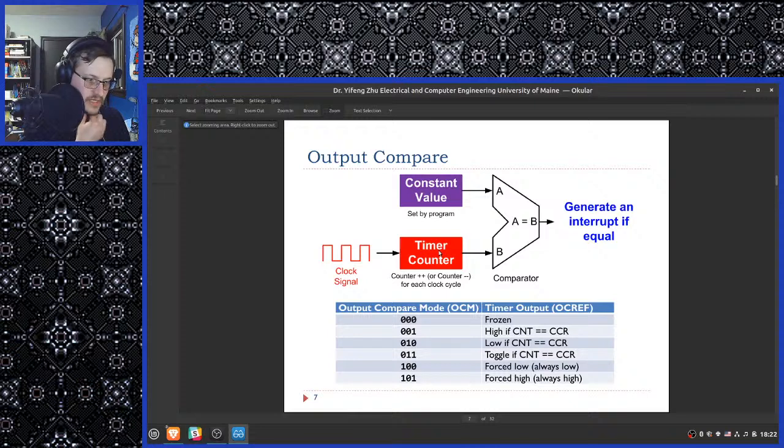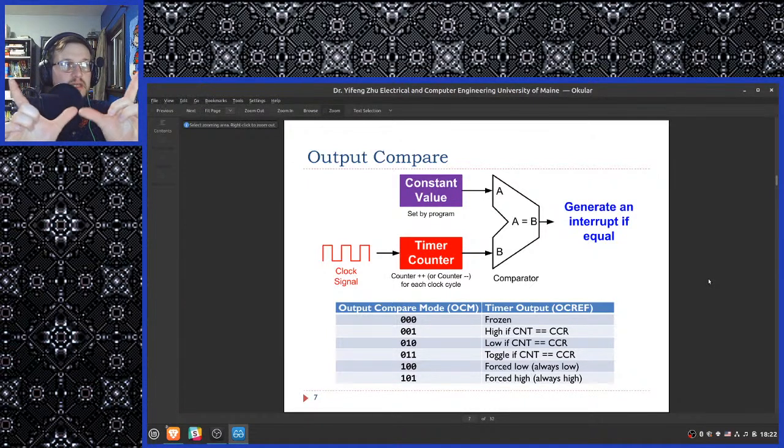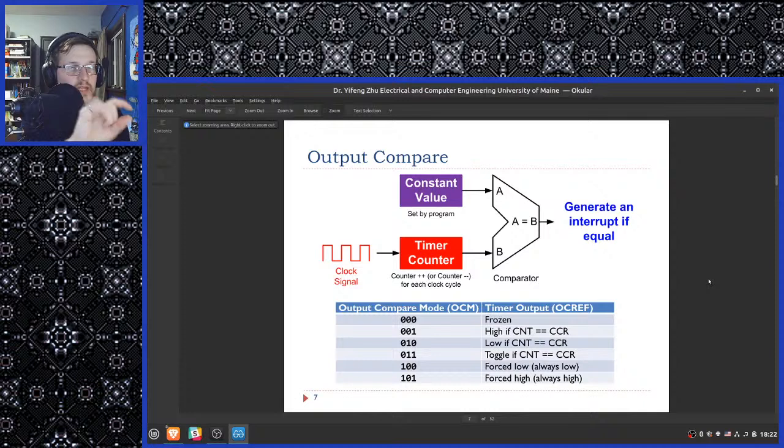You were thinking about it saving high or low and not the actual count. Yeah, there we go. Would encoders use the capture mode? Yeah, that's a similar thing to how an encoder would work. The same conceptual framework we're using here to determine the duration of an event could be used to determine the distance between two events on an encoder.